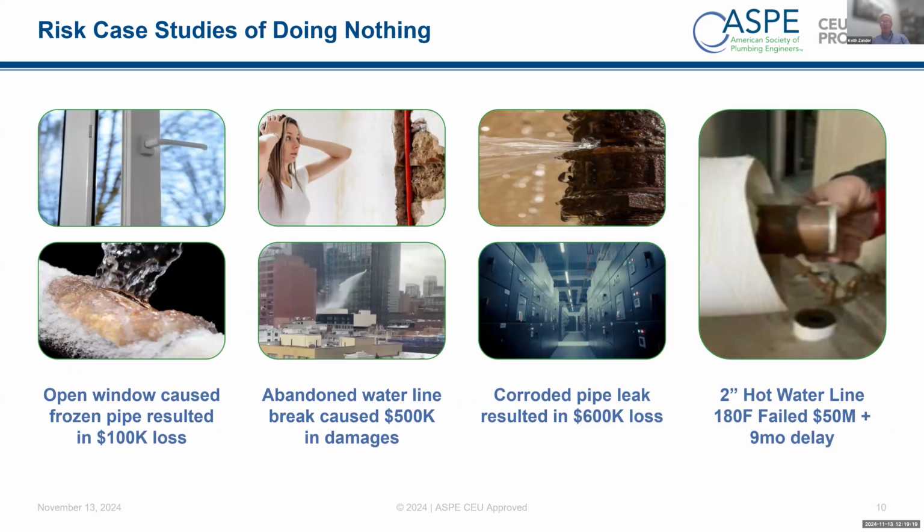Some of the things that people don't understand from a risk standpoint is open windows. Obviously, up north, you guys realize that piece of the puzzle, but we got called in on a job one time where a condo owner left the window open in October or November and didn't get back until the pipes froze up and caused significant damage.